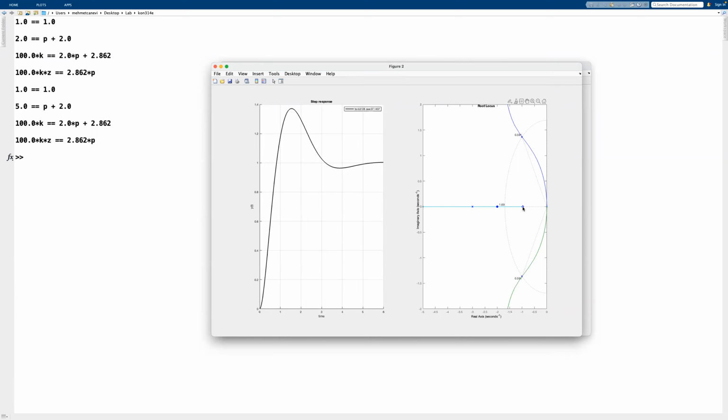Now, this is not quite a good solution, because we can see that, yeah, this one here is at, where is it? It equals 1. So this is basically s equals -1. And our real part is also equal to 1. So they're basically aligned here, almost. And in terms of dominant pole placement, this is not a good thing. We've seen before that when we enter the dominant region, the behavior of the system gets messed up. It will change. It will dramatically change, actually.